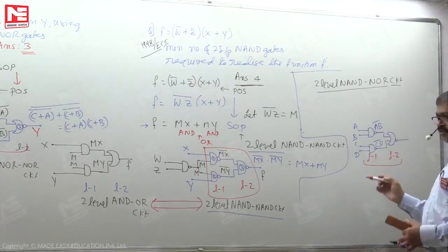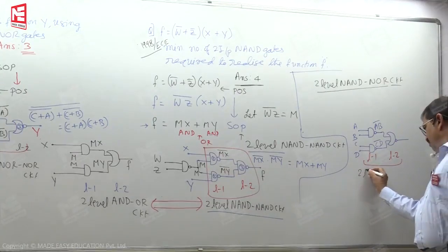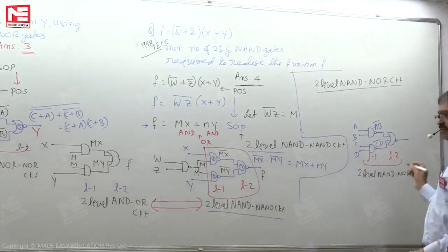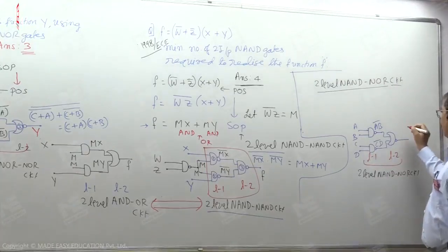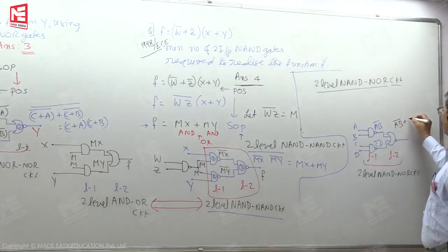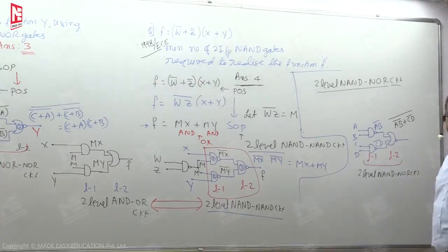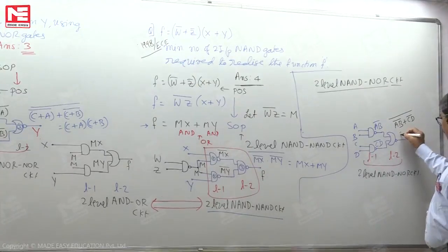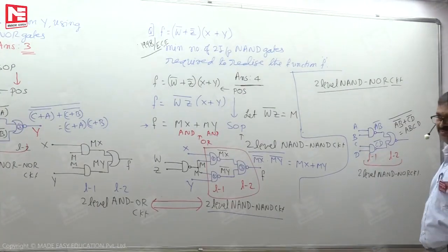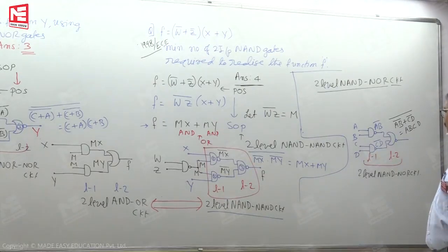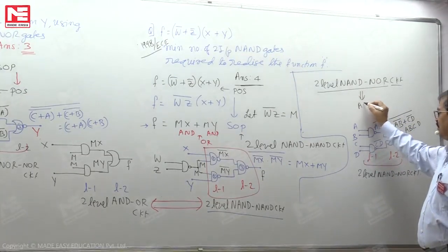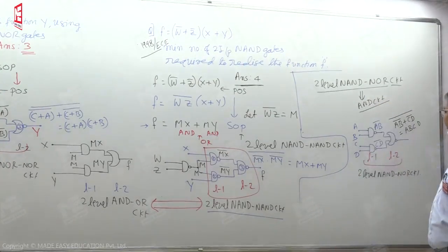On the whole, the circuit must be named a 2-level NAND-NOR circuit. Looking at the output, we have ((AB)' OR (CD)')', which by De Morgan's property is AB AND CD. So this 2-level NAND-NOR circuit results in an AND operation.